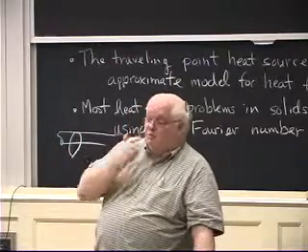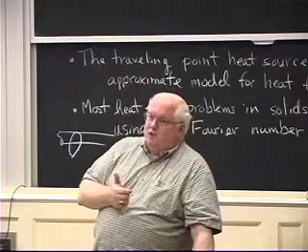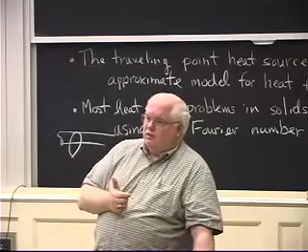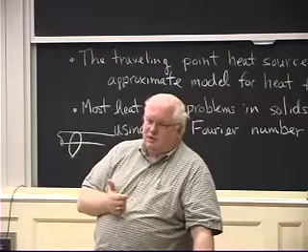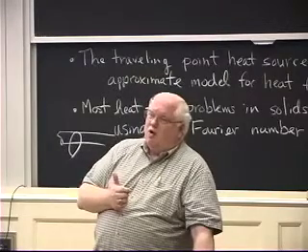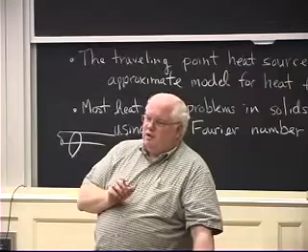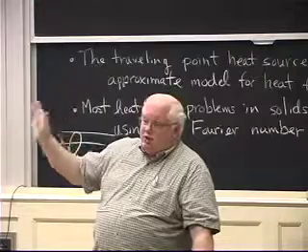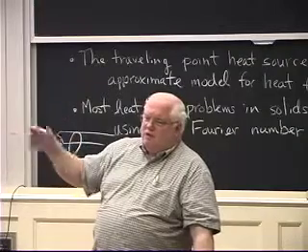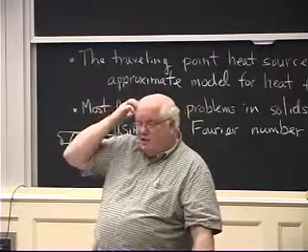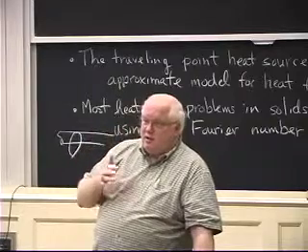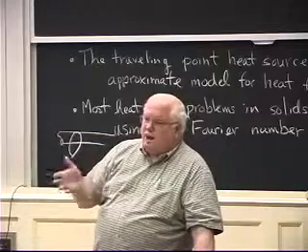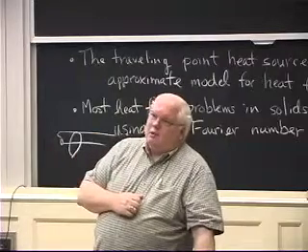The other problem is that people have looked at arc welding in space, but you don't have sources of low voltage and high current, and your energy costs in space are horrendous. So people have tried arc welding in space, and you get some very interesting behavior running vacuum gas tungsten arcs. Vacuum arcs are very different from the high pressure arc that we use here on Earth, and you get some very interesting fluid flow effects. They haven't been studied as much as they might because arc welding in space, for these other economic reasons, is not a practical thing. People have talked about electron beam.